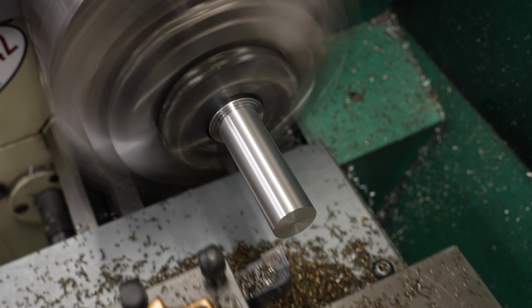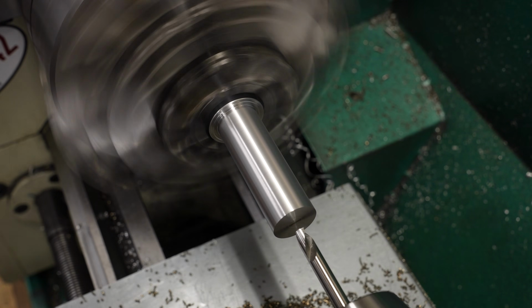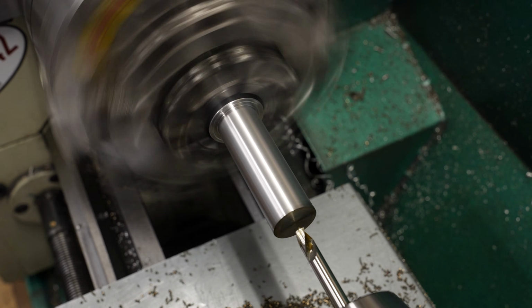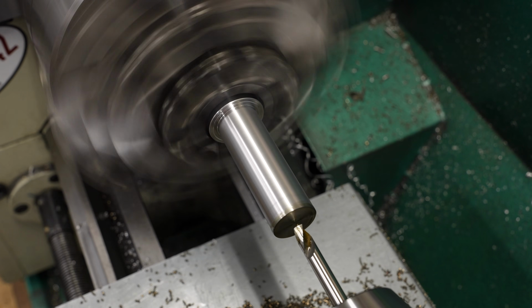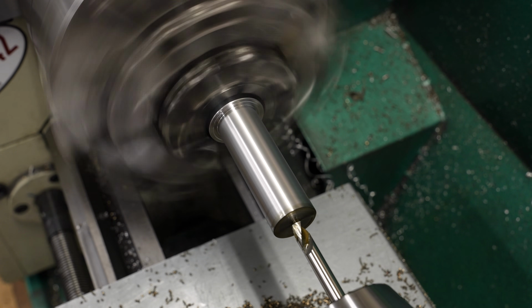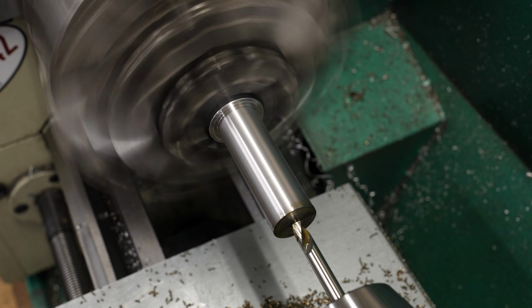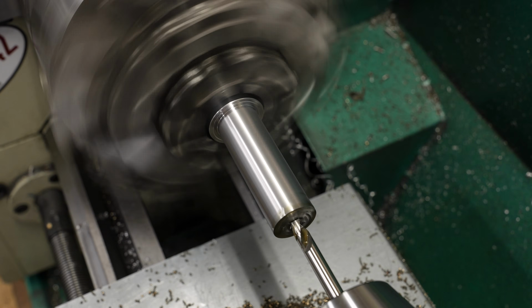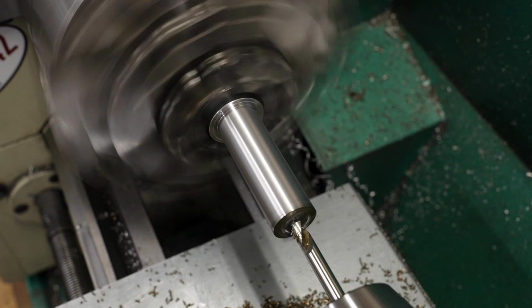Stop the power feed and hand feed up to the shoulder. And now let's go ahead and put the hole through it. Now I'm not measuring at this point on the outside because again, the part is really hot. I need to let it cool before I can actually get a dimension and bring it to a fine final dimension. And the drilling is going to heat this thing up as well, so we'll just go ahead and get the bulk shape of this roughed out.